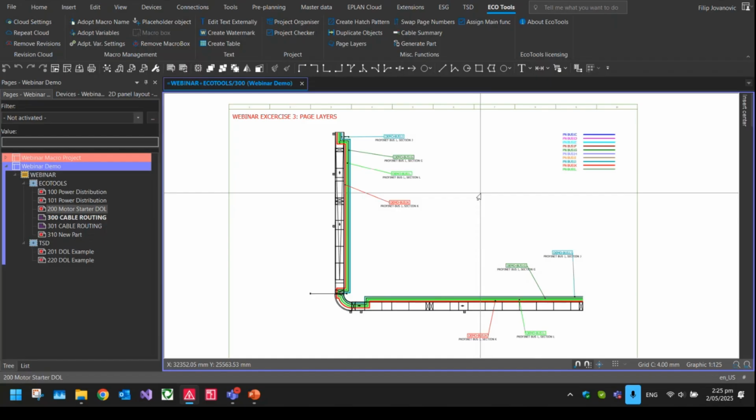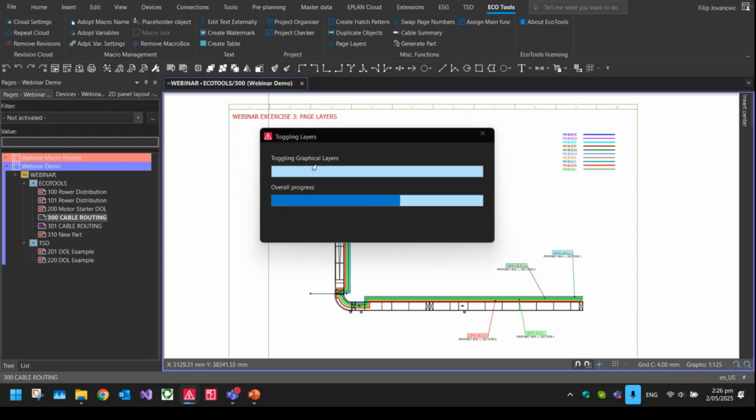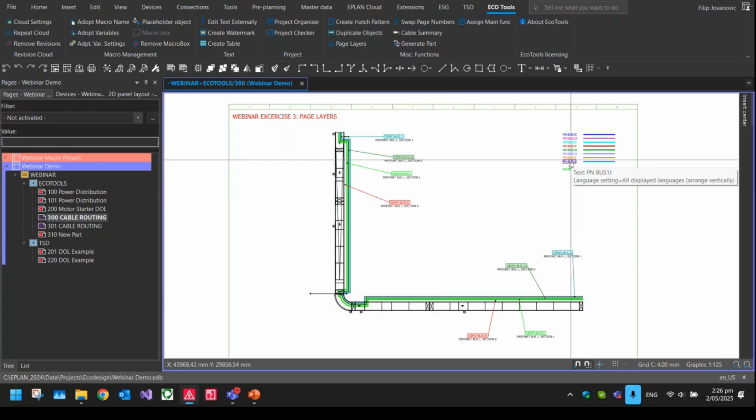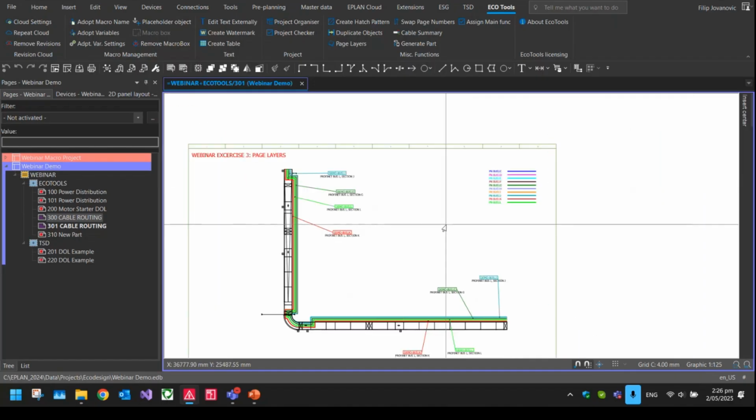So again, this feature is super useful, especially if you import FDL drawings from AutoCAD or DWG, and you want to hide invisible lines or hidden layers, this is the way to do it. And whatever you do on this page, the next page, let's see, like 301, will not be affected. So let me just give you a demo. If I hide K over here, you can see K's hidden here. Next page it won't be. So it just affects just the page.